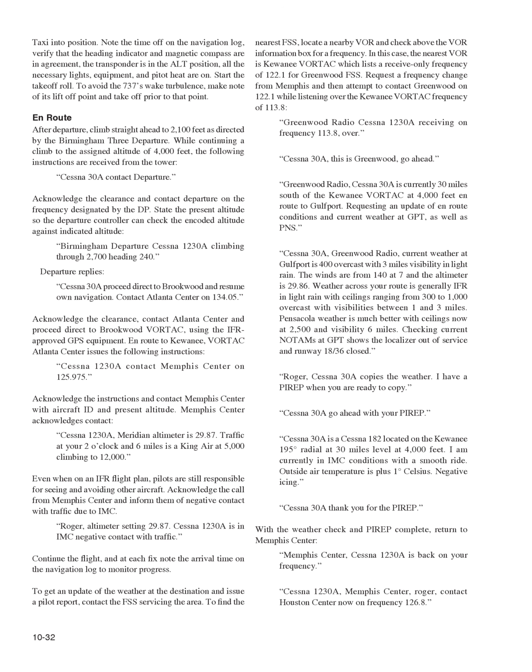To get an update of the weather at the destination and issue a pilot report, contact the FSS servicing the area. To find the nearest FSS, locate a nearby VOR and check above the VOR information box for a frequency. In this case, the nearest VOR is Kewanee VORTAC, which lists a receive-only frequency of 122.1 for Greenwood FSS. Request a frequency change from Memphis and then attempt to contact Greenwood on 122.1 while listening over the Kewanee VORTAC